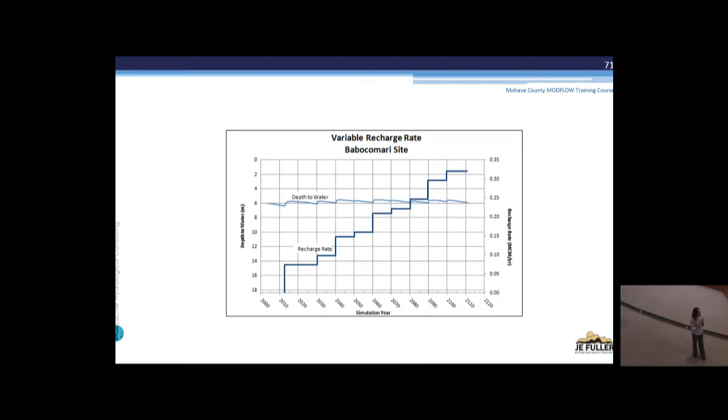And that's important to know: you don't have to have the whole problem fixed today, but you have to keep up with the damage that's being done by the Kona depression that's eating into this system. So as the impacts of pumping are spreading out, we have to compensate by adding more recharge over time. You don't need a huge amount of increase each year, but you do need to keep increasing it over time. Yes, this is a transient model based on increased population and pumping over time.